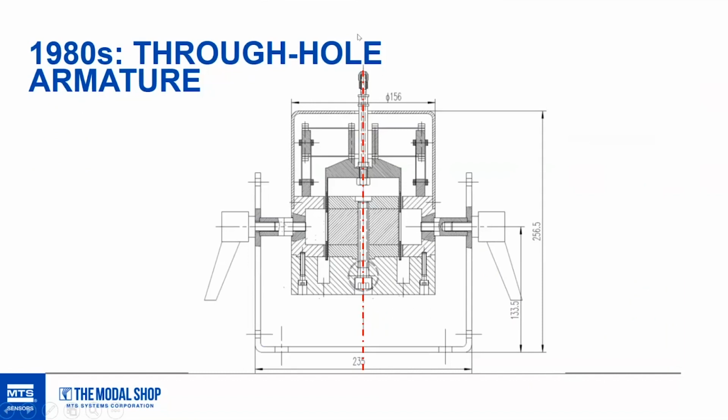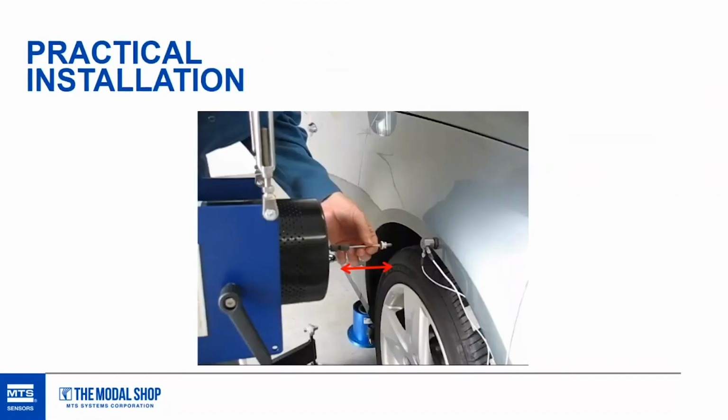The stinger can slide through the shaker body and be attached to the shaker by just a chuck and collet system that basically grabs the stinger in its place. And it's easier to explain that by just looking at a short video we have here. I hope that shows correctly through the webinar.